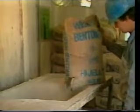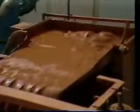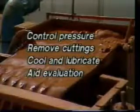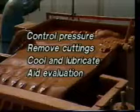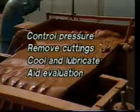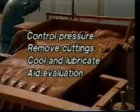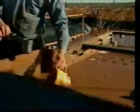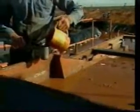In some cases, oil is added to the fluid, or the entire system may be converted to an oil-based rather than a water-based mixture. In any case, the drilling fluid must have properties which enable it to control subsurface pressures, remove cuttings from the hole, cool and lubricate the drill stem, and aid formation evaluation and productivity. Let's look at each of these functions. The drilling fluid controls pressure, as we've already mentioned, by imposing hydrostatic pressure against permeable formations and preventing flow.